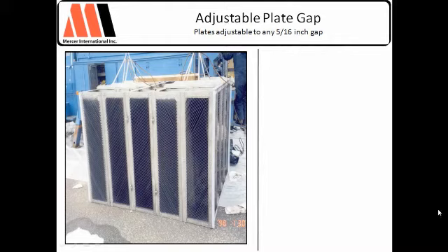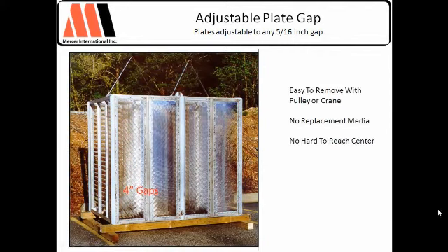This one's used at about 180 Fahrenheit. Years later, still looking really good. With every plate in place, 45 micron removal, we're about at the highest efficiency available in the industry. Now, that's with a cross-flow design, chimney zones, flat plate. These things can go a quarter, 6 months without fouling. Real good. And the next slide shows a client who said, look, we can't put the time into maintenance.